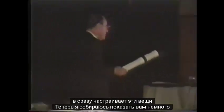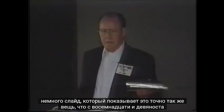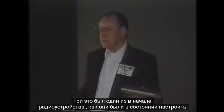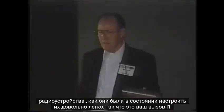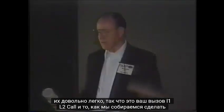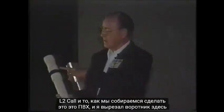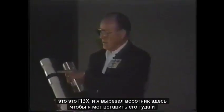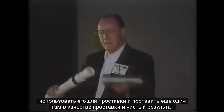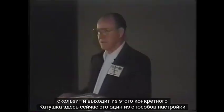So with that in mind, one of the problems that people run into immediately is tuning those things. Now, I'm going to show you in a little bit a slide that shows this exact same thing from 1893. It was one of the early radio devices, and how they were able to tune them fairly easily. So this is your L1 coil, L2 coil, and the way we're going to do this is PVC, and I cut a collar here so that I could slide it on there and use it for a spacer and put another one there as a spacer, and the net result is that this thing fits almost perfectly. It slides in and out of this particular coil here.